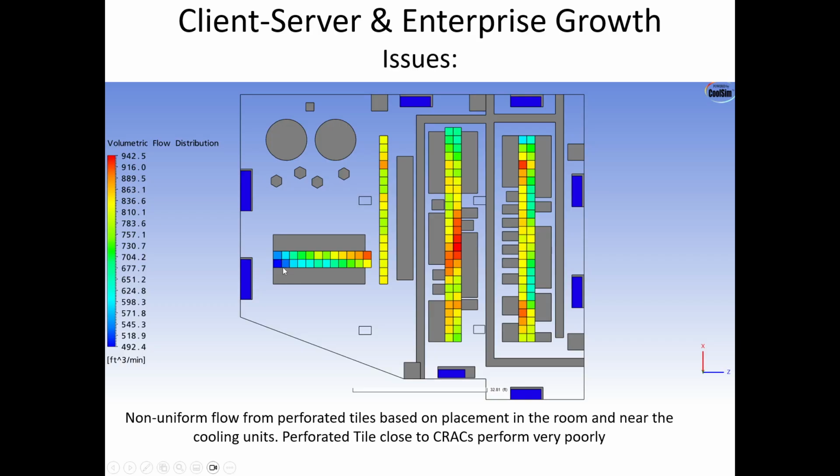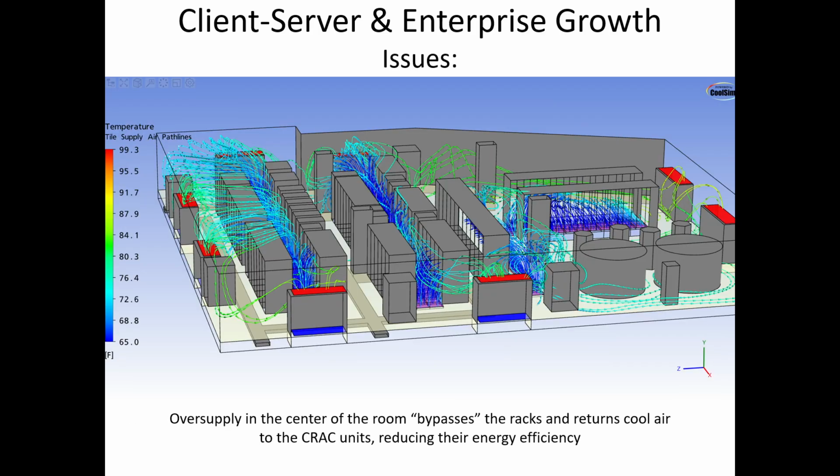It's primarily dynamic. In a perimeter design like this one, the static pressure is always highest in the center because all of the flows come to the center. Their dynamic velocity declines. Their static pressure rises. So the best place to put high density equipment in a room like this is right in the center because that's where the static pressure is the highest. Furthermore, positioning of the cooling units can cause some underfloor effects to occur. It is not uncommon to get low pressure areas in certain regions due to vortices under the floor caused by the positioning of the cooling units themselves.